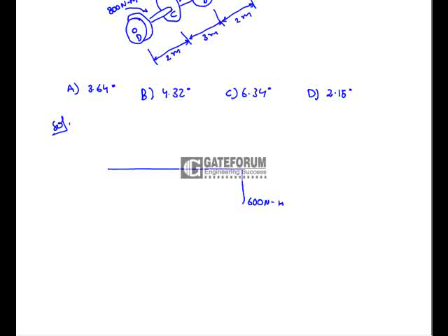Until the B there is no change in torque. So here it is position A. At the B there is 900 Newton meter applied in the clockwise direction, so that it is positive. Now draw a line above the reference line. So it is 300 Newton meter here. So this is the reference point B.